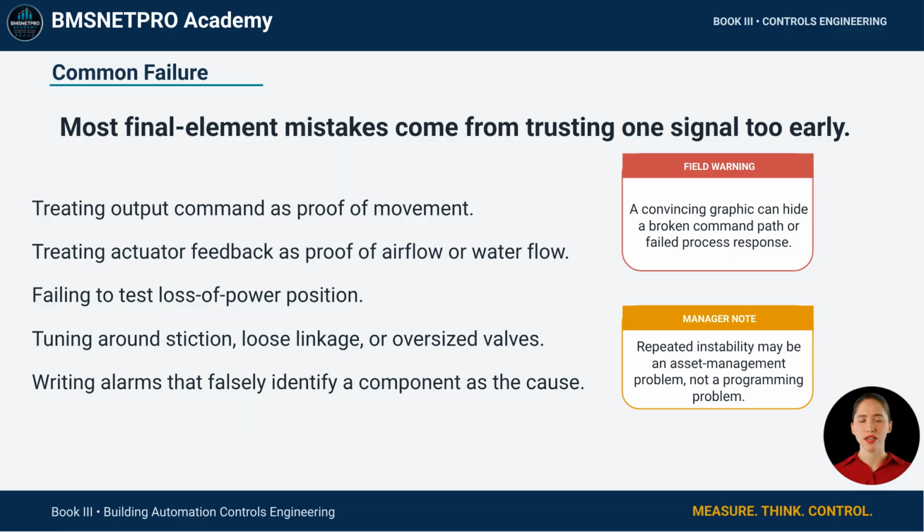The final common error is alarm wording. Do not write an alarm that says cooling valve failed when the logic has only proven insufficient cooling response. Alarm the evidence you have and let the technician investigate the cause.